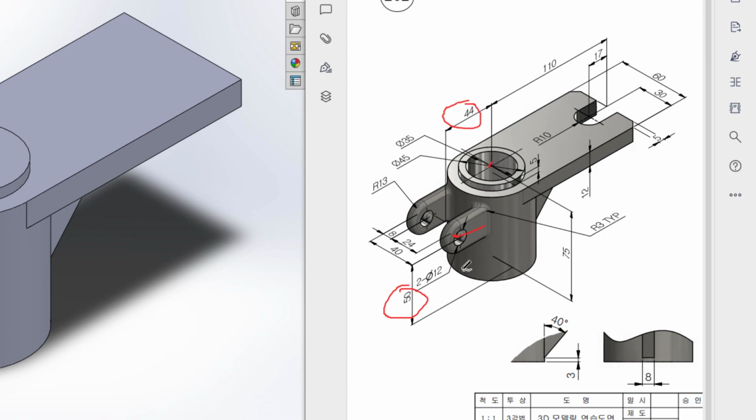After that I can see this has a radius of 13 unit. So I'll draw one offset line 13 unit from here to here, and I'll draw another offset line 13 unit from the other side. Okay, then I will close the shape, and as it is a circular surface I will extend this line a little more here.